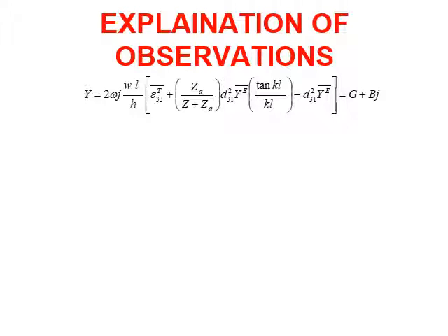What does T indicate in the superscript? T indicates that this quantity is measured at constant stress. And similarly, the bar above epsilon 33 indicates that this is a dynamic parameter.